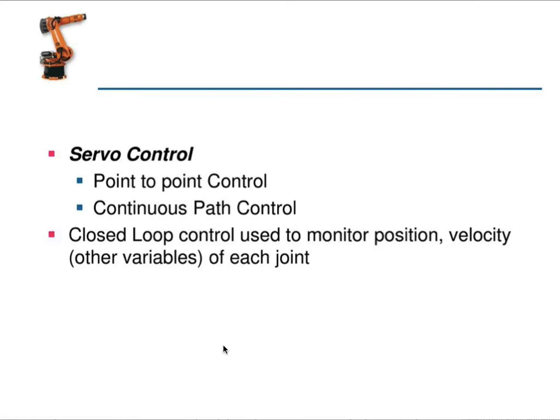These are servo controls, that is point to point control, where the controller has a memory for recording not only the sequence of the motions in a given work cycle, but also the locations associated with each element of the motion cycle. These locations and their sequences are programmed into memory and subsequently played back during the operations.